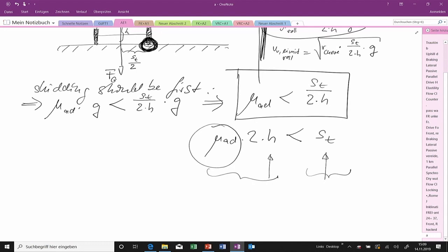So we have also this oscillation, and this also comes with a certain frequency which is very, very similar to that frequency given for this roll oscillation. So roll oscillation and yaw oscillation have very similar frequency. This creates a system which is very easy to excite to very, very strong oscillations, so with large displacements, if the steering action is done with the right frequency. Yeah? Is this plausible?